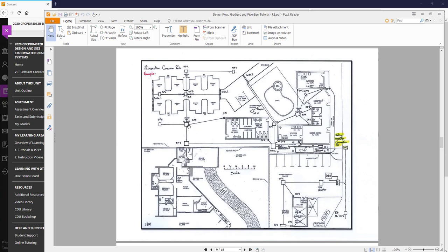Then as we go through, SP5 captures the load of everything that goes into SP3, plus what goes into SP6 and what goes into downpipe 1, in addition to what it captures for itself, and that will be the loading that ends up going on this pipe here. So that's how we're going to do it.